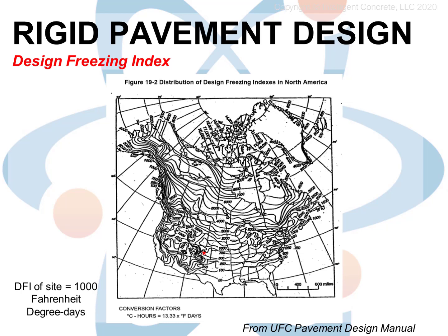At Thule Air Base in Thule, Greenland, about 900 miles from the North Pole, special ducting was built under the floors of hangars to keep the permafrost from thawing. The design system didn't work very well, and the ground thawed. The floors of the hangars sank more than 2 feet, rendering them completely unusable. In the repaired system, an entire refrigeration system with cooling coils built under the concrete slabs had to be designed and installed to keep the ground frozen, solid, and stable.